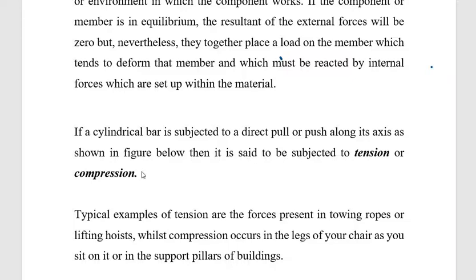That is, if the forces act towards each other to push or shorten or reduce the length of the object, then it is under compression, and the stress that will be produced will be compressive stress. If it is subjected to a pull and therefore there is an increase in its length, then it has been subjected to tension and therefore the stress that it is subjected to is called tensile stress.